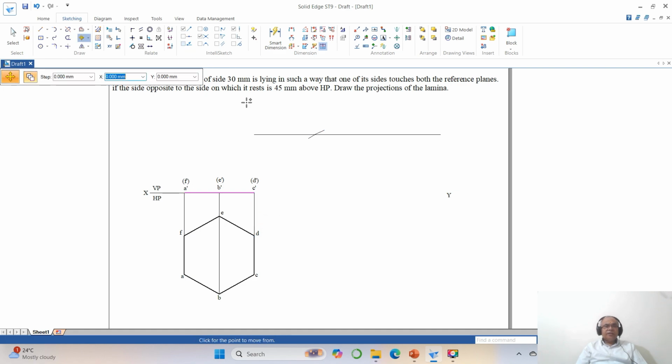So you remove point on element now. You take this endpoint, and I want to keep this endpoint such that it should be the center of this arc. So to do that, I will go for center point and remove endpoint. Now you take the cursor here on the arc and then bring that cursor down so that the center point is highlighted. The center point means it is always the center point of the circle we are talking about. So once you get this, you just click on the first button of the mouse. Now you got this figure.